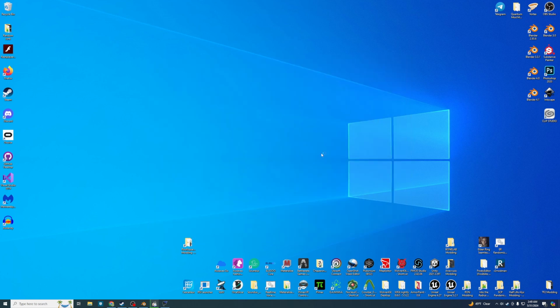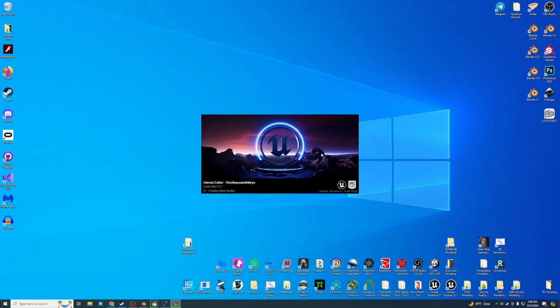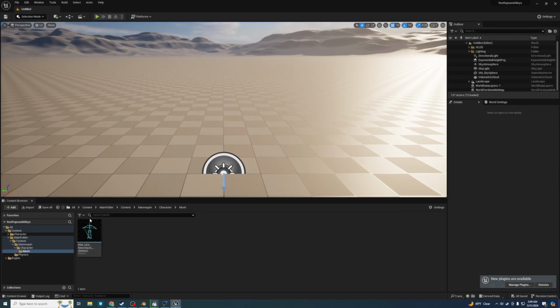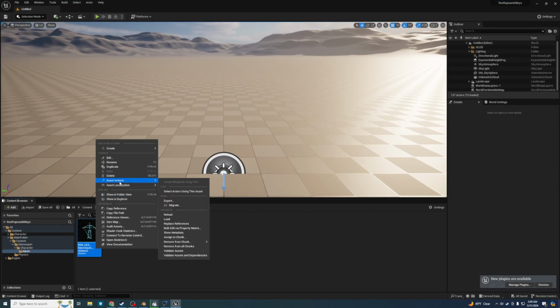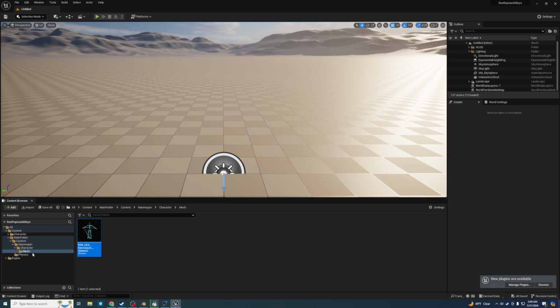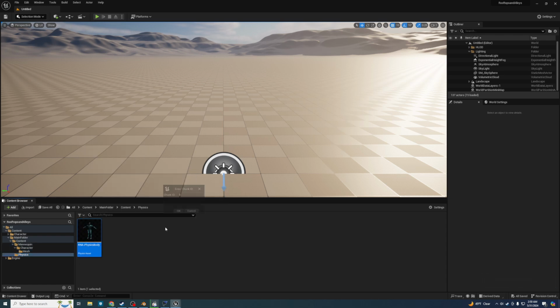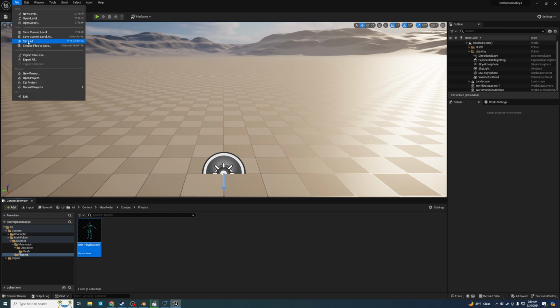So we'll open this. Okay. And now we're going to do one last check. I think this should still be set to 0, but let's just go ahead and do it again. Not going to hurt. Asset actions, assign the chunk, 0, file, save.